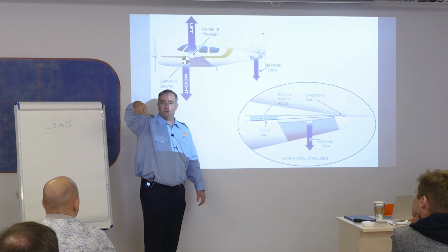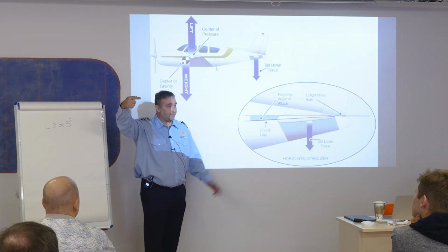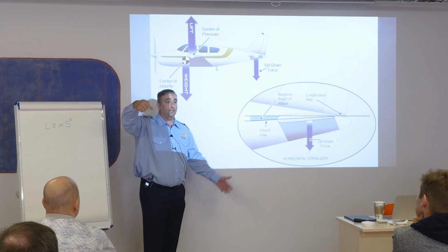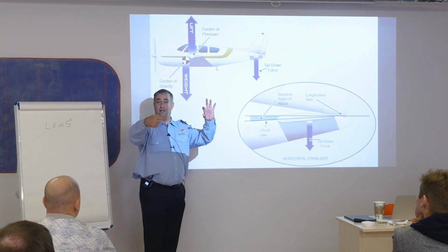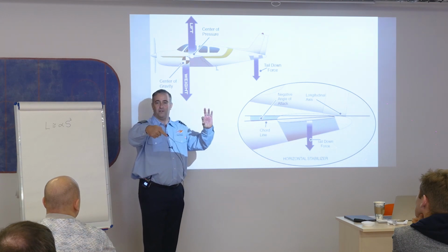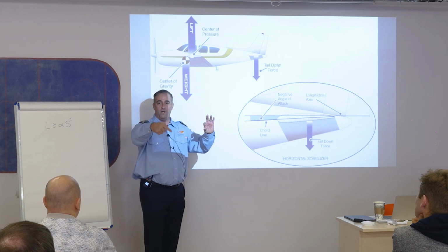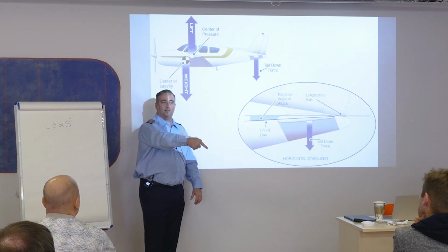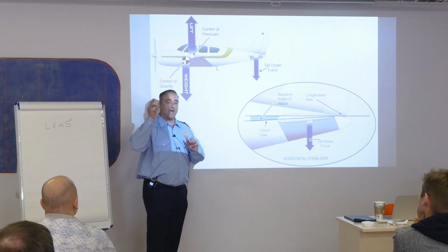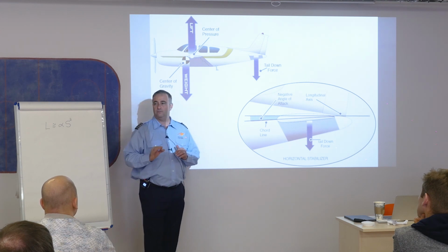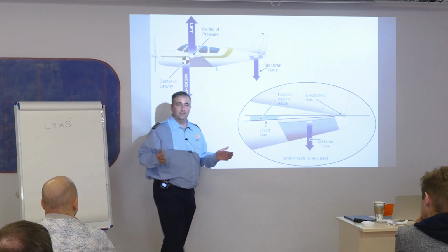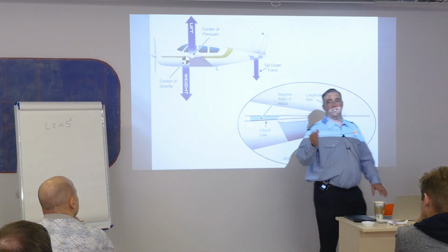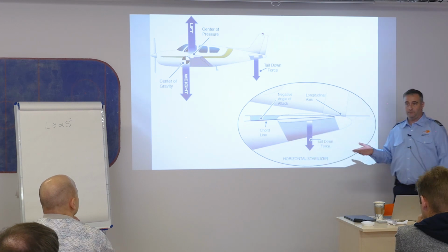Initially, it goes down, but it won't go down too far. It's designed not to go down too far. Then the aircraft will increase speed and it will pitch up, but not all the way level. It'll be less than it did last time. Then it goes down a little bit less than it did before. And after a series of oscillations, it will have a perfectly straight path. Okay? The airplane is stable. That's positive static and positive dynamic stability.